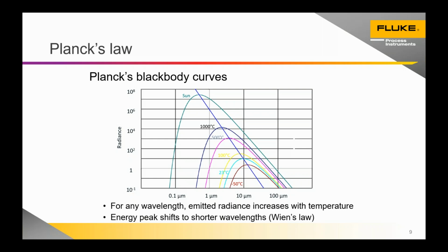Okay, so Planck's law. Every infrared temperature manufacturer is subject to Planck's law. It makes things in some ways very easy. It can add confusion sometimes, but generally, Planck's law helps us to characterize the output from the detectors that we use, in how we build up essentially our energy to temperature conversion in our devices. And we observe Planck's law because it really defines everything we do.